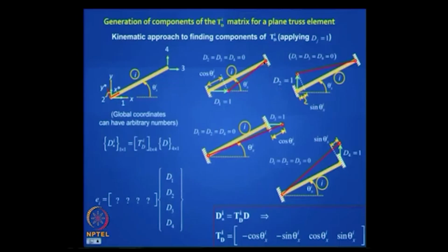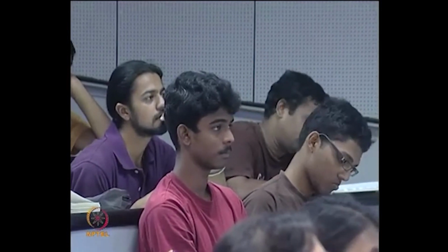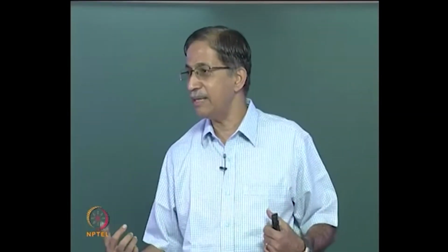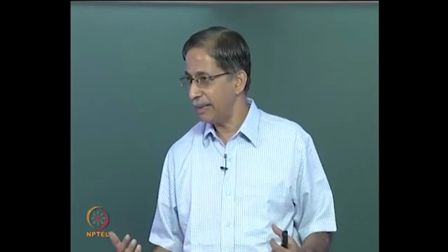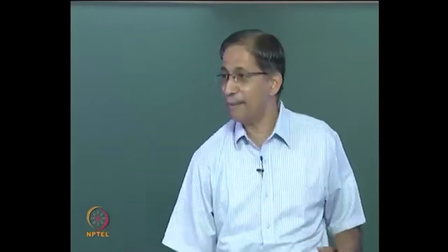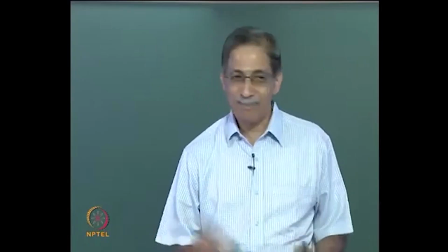But when I pull the right end here, I get a plus sign because you can see the red line has elongated, and when I lift up the right end, I get elongation, right. So what I have written here, the displacement transformation matrix gives me the element elongations caused by a unit translation at the left end and the right end, keeping all the other degrees of freedom clear. So I get minus whenever I push the left end, and I get plus when I push the right.